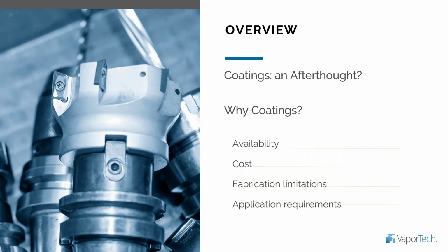You can select the material knowing that you're going to apply a coating on top of that. And that's quite important. One thing that comes to mind is when that comes into play. For instance, if you have components that have very tight tolerances, you must be aware that the dimensions of the coating will add to the dimensions of the part. And therefore, when you prepare your substrate, your tool or your component, you have to take that into account. So just have that in mind.